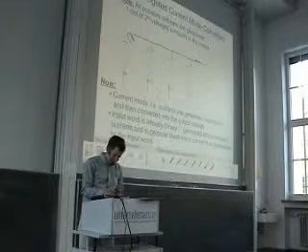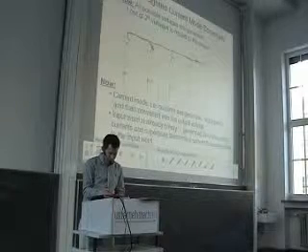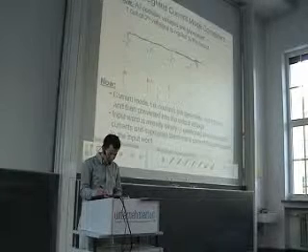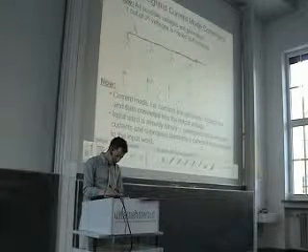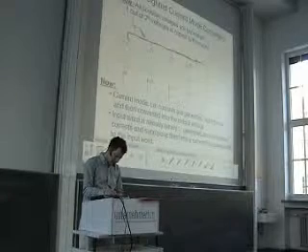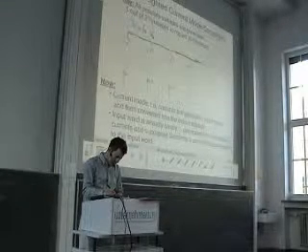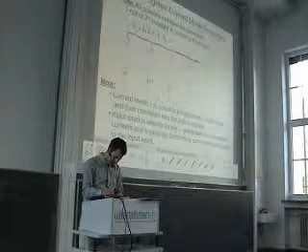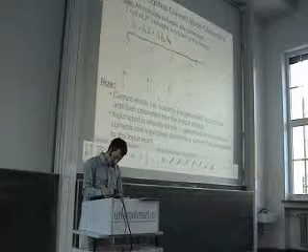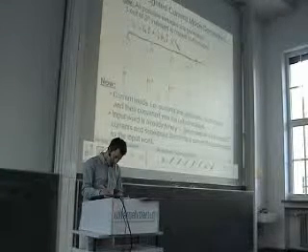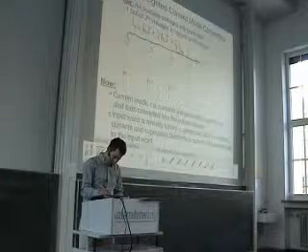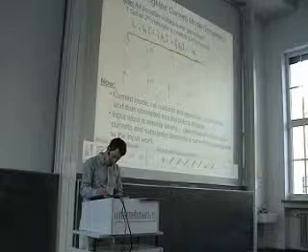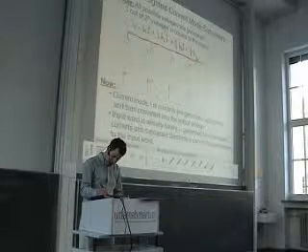So by a structure like this, we add all these currents together because the total current flowing here is given by IF equal to B1I plus 1 over 2 B2I plus 1 over 4 B3I plus 1 over 8 B4I.